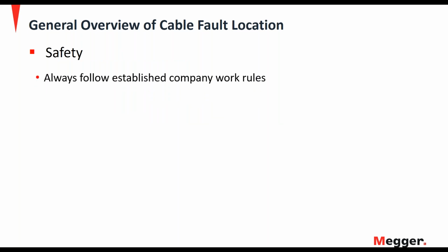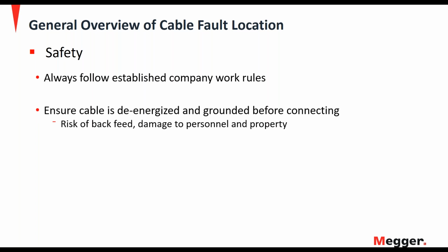Obviously, when you're working with a cable fault locating system out in the field, you're going to follow your company's established safety rules. And that includes some form of making sure the cable is de-energized and grounded before you connect your test set. You want to reduce the risk of backfeed damage to anybody or property.